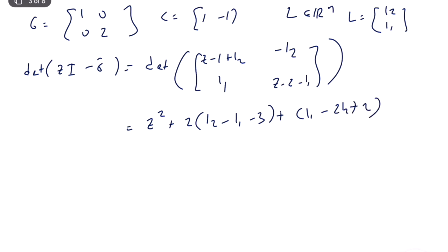Okay, so what do we want? In this problem, I want my lambda 1 and 2 to be equal to 0. So I want a deadbeat observer. So what is a deadbeat observer? We know that a deadbeat controller and a deadbeat observer are similar. And it's even more practical because we are only simulating the system, so technically the magnitude of L is not very critical. A deadbeat observer estimates the actual states of the system in finite time.